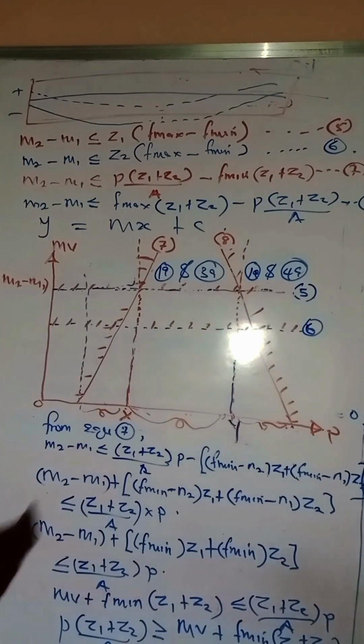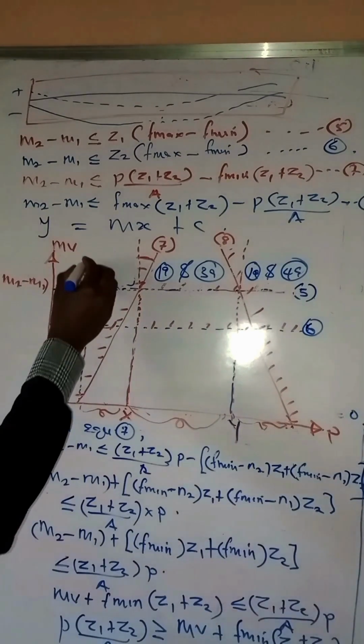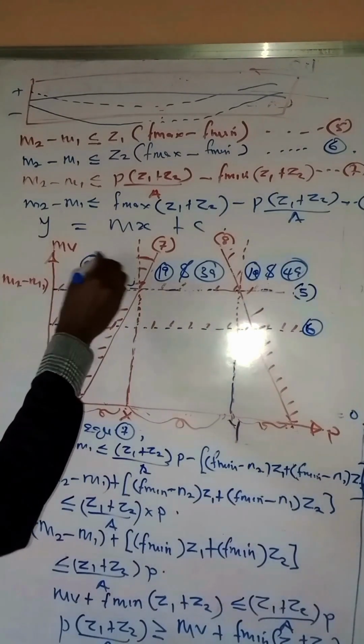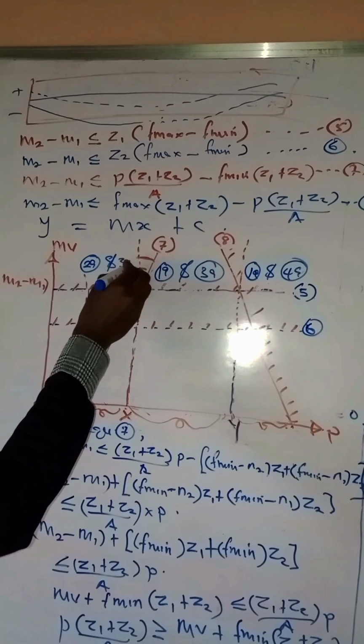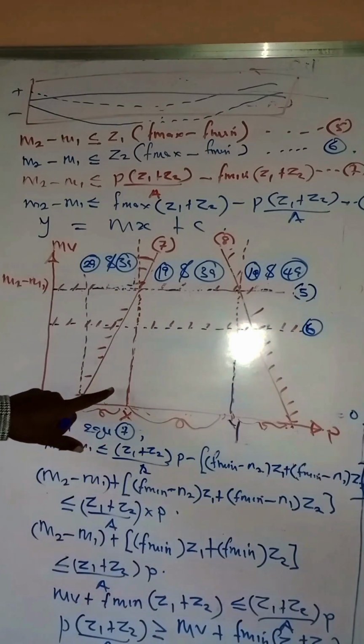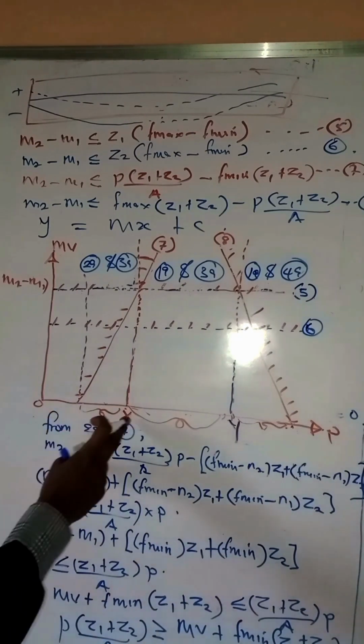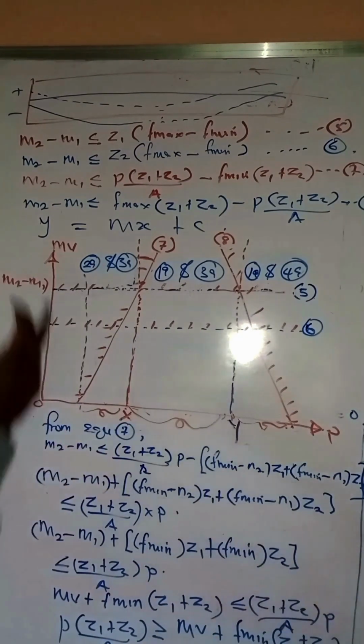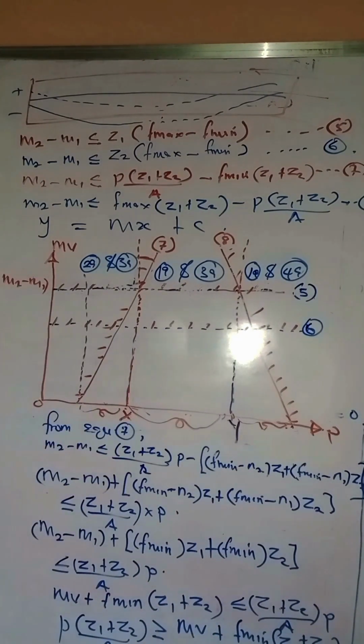So wherever a pre-stressing force lies between here, this cable equation for the cable zone should be taken. Similarly, we have here equation 2A and equation 3A. Whenever your pre-stressing force is chosen between X and this point, equation 2A and 3A should be chosen for the cable zone determination.